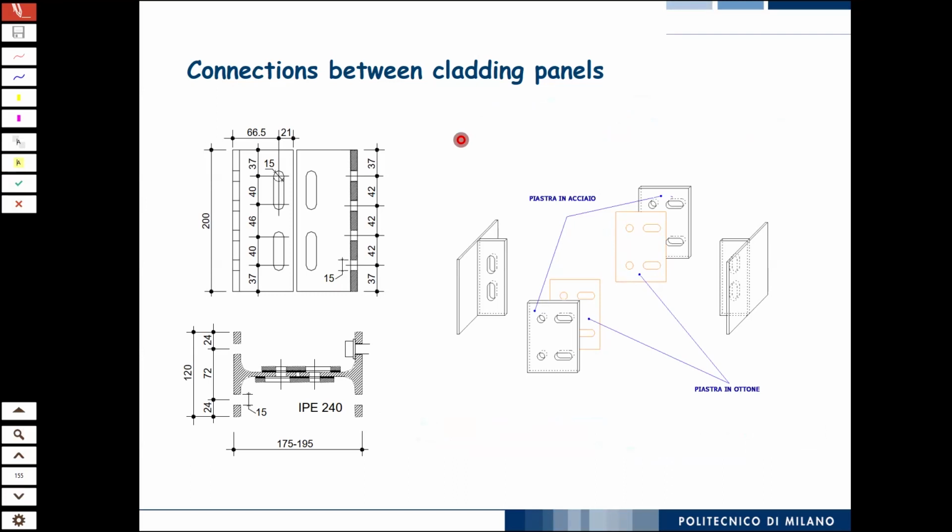Actually, these elements here are steel I-beams cut into halves. So these you attach to the left panel. These you attach to the right panel. And provide this with these slots. Then when the two panels come together, you complete this sandwich.